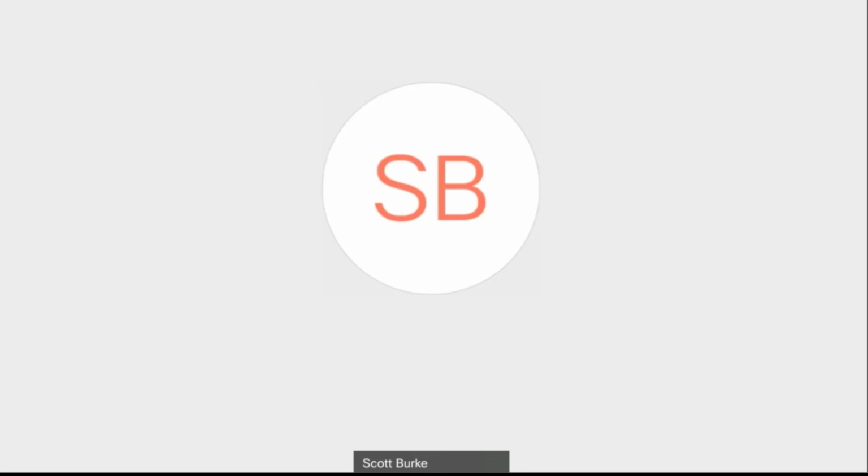So yes, you can put AutoCAD files into BIM 360. You absolutely, via the desktop connector, can link details into your Revit sheet if you want. So I'm assuming that's what we're talking about here, so that you can have a folder called details, individual details, and you can link them into Revit if you need to do that. You would just need to use a desktop connector for non-Revit files, that's all. But again, the advantage is they all still live in the cloud, so that's certainly a nice thing.